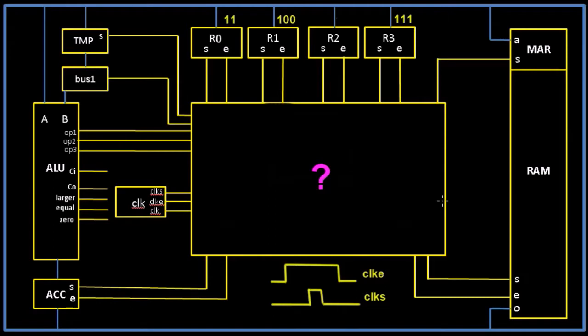So the example we're going to work through is the add instruction. So we're going to add 2 numbers together. So we're going to have a number in R1. So the number we're going to have is number 4. So that's the binary for the number 4. So it goes 1, 2, 4. And we're going to have a 3 in register R0. So that's the binary for 3. We're going to add both of them together, and we're going to put the result into register R3, and the result is 7, and that's the binary for 7. So it's 1 plus 2 plus 4, which is 7.